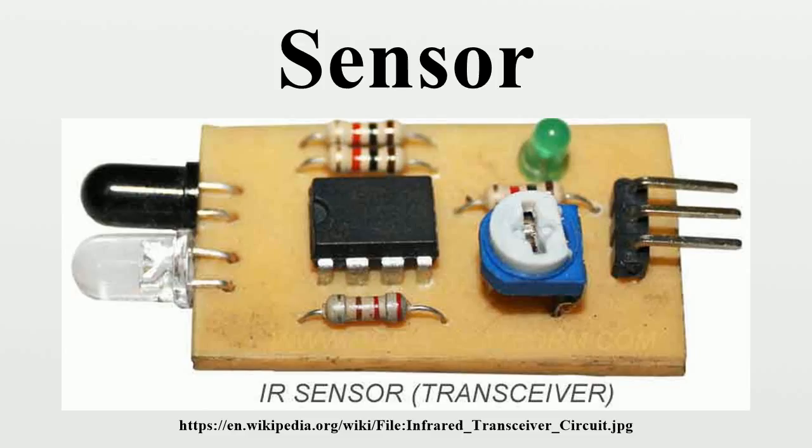creating a different offset error in one direction than in the other. If the sensor has a digital output, the output is essentially an approximation of the measured property. The approximation error is also called digitization error. If the signal is monitored digitally, limitation of the sampling frequency also can cause a dynamic error, or if the variable or added noise changes periodically at a frequency near a multiple of the sampling rate, it may induce aliasing errors.